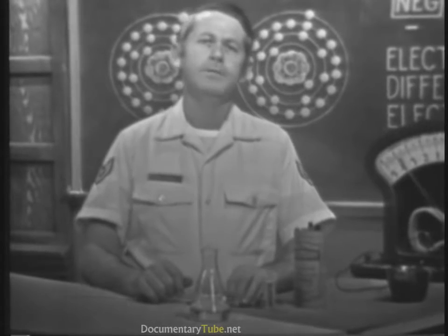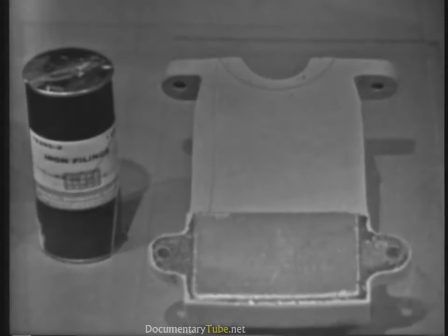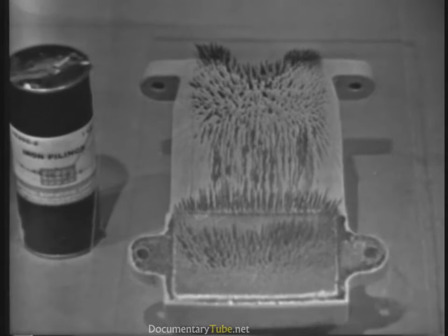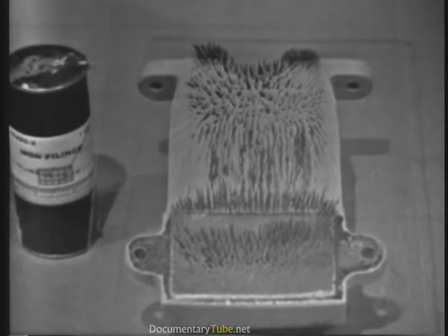Another popular way is by mechanical means, commonly called the induction or generator method. In this method, all that's required is a magnetic field, a conductor, and motion between the two. Now, a magnetic field is similar to the field around a charged body. We can get an idea of how this field exists by using iron filings and a magnet. I'll sprinkle some filings on the glass covering this magnet. Notice how the filings form into lines, indicating the shape of the magnetic field.